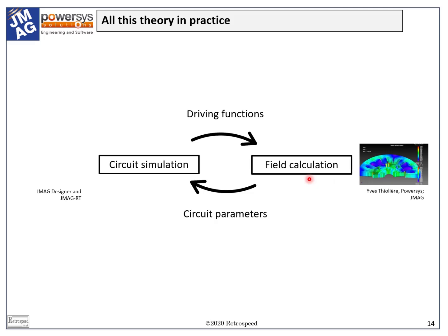Real windings are not sinusoidally distributed. In fact, it is impossible to make a truly sinusoidal winding distribution. For that reason, we must use Fourier series to perform a harmonic analysis of the actual winding and extract the fundamental space harmonic for purposes of the performance calculations.